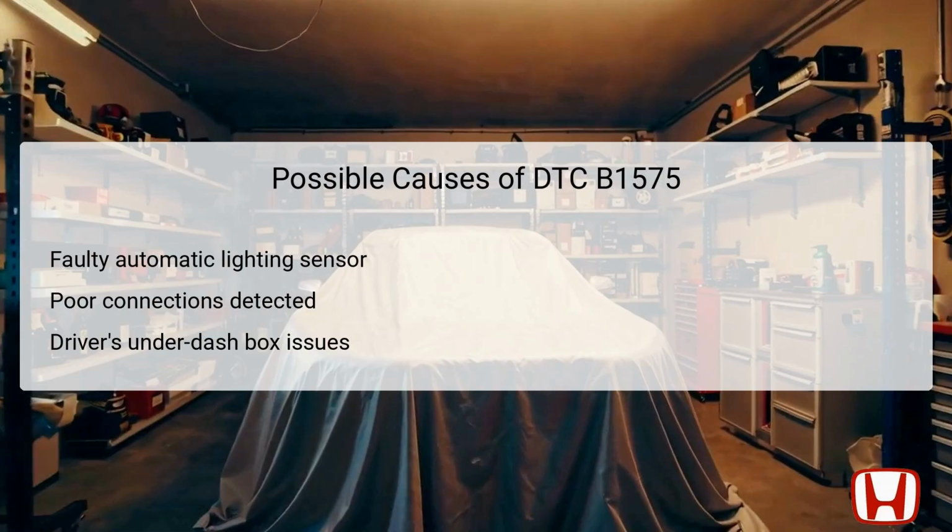the sensor's malfunction. Additionally, issues within the driver's under-dash fuse/relay box, such as damaged terminals or internal failures, can exacerbate the problem. Correctly diagnosing these potential issues involves thorough inspections of both the sensor and the wiring involved. Replacement or repair of any defective components is typically necessary after confirming the exact failure point.